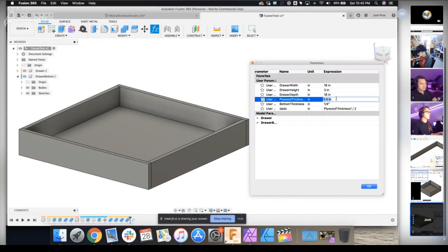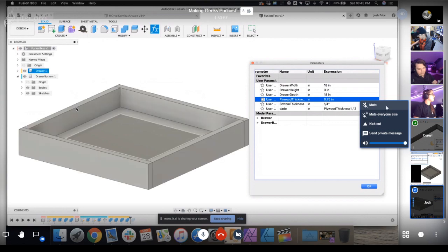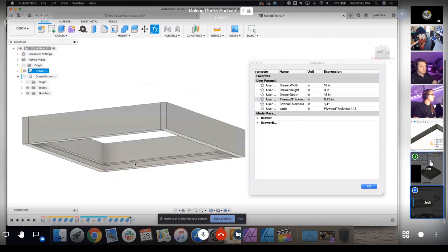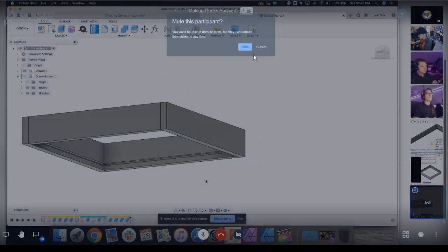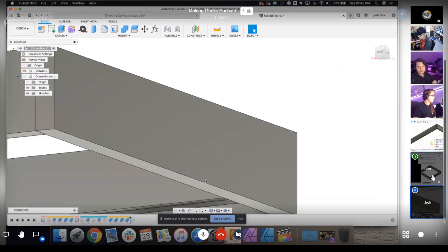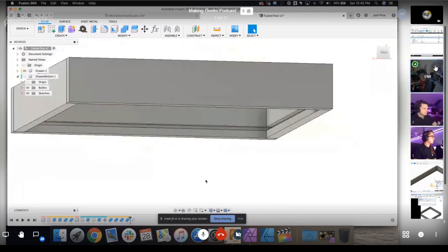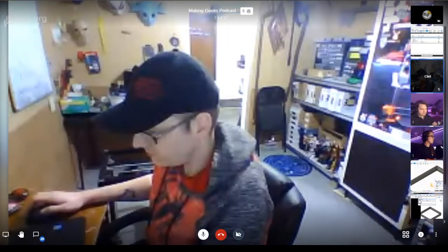And we don't have any 1/2 inch plywood. All we have is 3/4 inch plywood, so we're going to change that too. Bam. Everything updated. Even your dado updated. Hide the bottom. Even your dado is still half the thickness of that piece of plywood, which would then let you know where to set your table saw height, where to set your fence.